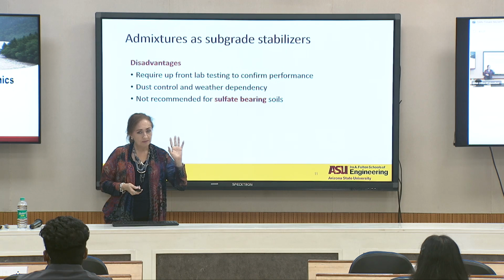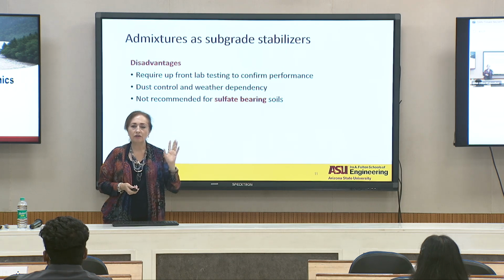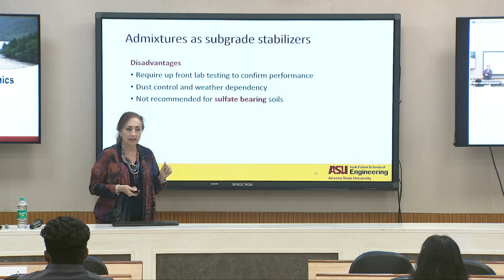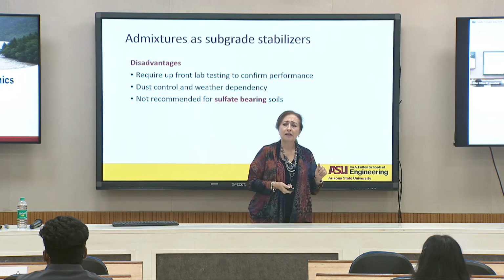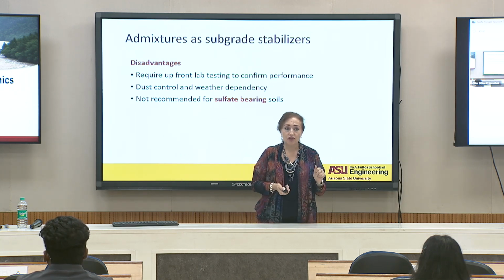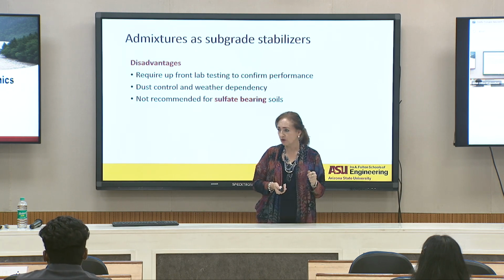Okay, so always think that when you're going to stabilize or just add some lime into your soil, or any product that has calcite in there, you need to first of all check for sulfates in this soil. Okay, this is very important. I'm going to show you why.